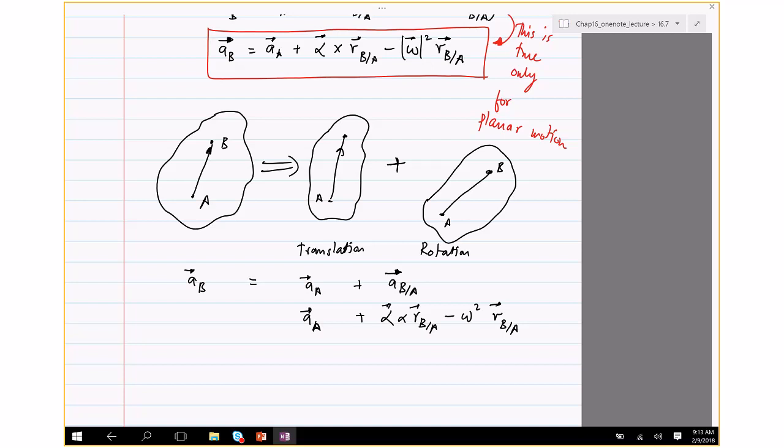The other way to do it is to write that equation as components, the magnitude and direction, and resolve components in the x and y direction, and then solve for the unknowns. So pictorial way, which is the second way, magnitude and directions, or as vectors. We'll solve some problems where it will be clear. I will not use the pictorial way because it essentially boils down to using the same thing, except that you're just showing arrows, but it's absolutely fine if you do it that way.